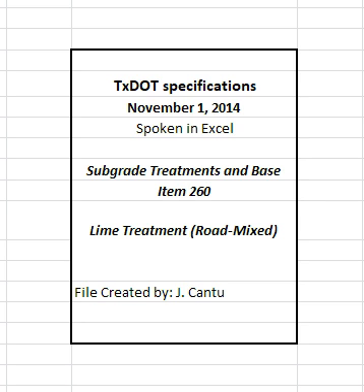2.1 Lime. Furnish lime that meets the requirements of DMS 6350, lime and lime slurry, and DMS 6330, pre-qualification of lime sources. Use hydrated lime, commercial lime slurry, quicklime, or carbide lime slurry as shown on the plans. Do not use quicklime when sulfates are present in quantities greater than 3000 ppm. When furnishing quicklime, provide it in bulk.